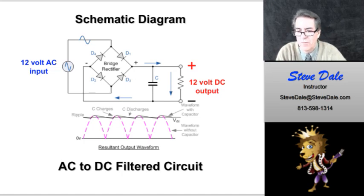Let's say it's 12 volts. So then you've got alternating current coming through the transformer, as you see at the top of this schematic diagram here, the little blue sine wave there. And then it goes into a series of diodes, because we have to take that alternating current and change it into direct current.